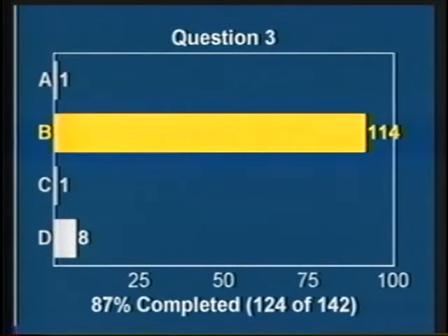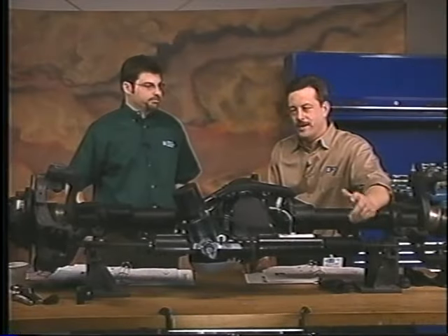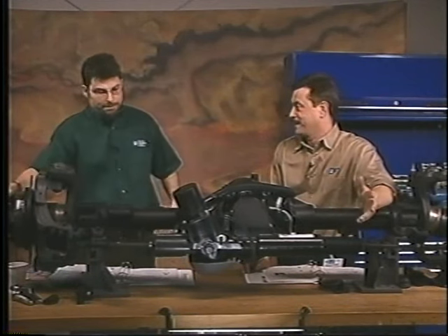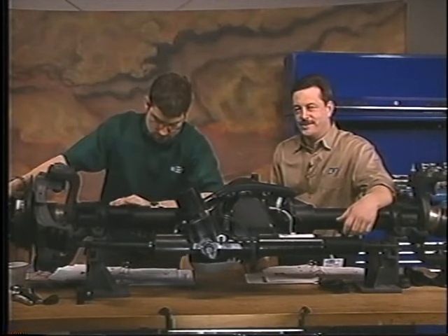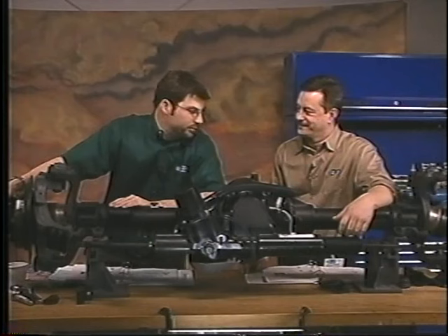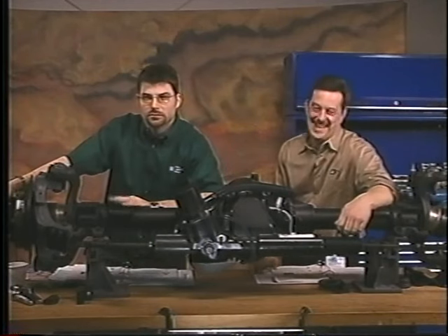All right, there we go, Mike. Let's take a look at our results. Everyone's doing a good job. It's pre-indexed. It has that shipping pin installed in it. That's it. Got to line that thing up. If you don't have a shipping pin, just set it at the 2.5 volt mark before you install it on the column. All right, just in case there's a smart aleck in your shop. It's hard to believe, but, you know, someone sees it on your bench, pulls the pin, gets a twist for you. I think of a few people around here I'd like to pull that pin on. Yeah. All right, what's next?